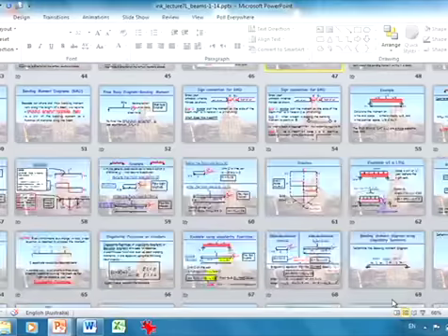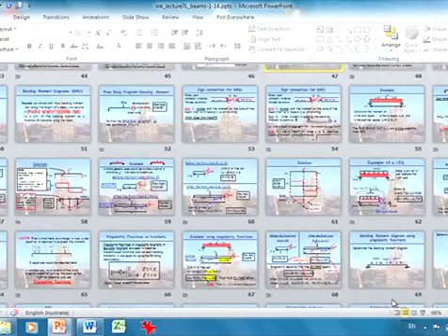I just have a couple of quick project questions. Do we need to consider loads perpendicular to the trusses, like cross bracing or anything? Remember when I said when you've got steel, you calculate the weight of your truss and then you increase that by 20% to allow for ancillary steel. So we don't have to worry about it, it's just the trusses having vertical loads, as stick diagrams. Yes, that's enough to design a truss, that's excellent.